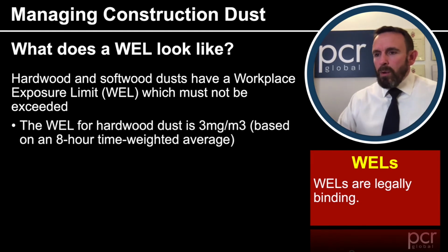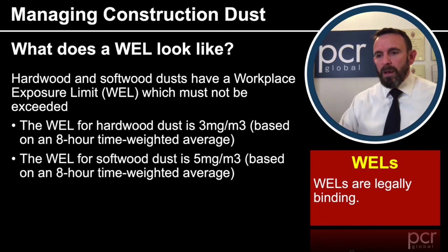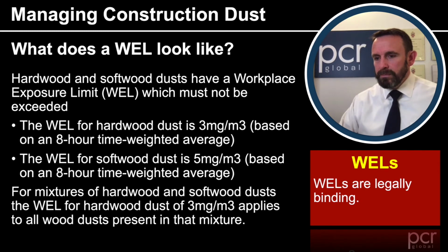So there are WELs for hardwood and also for softwood, and they also must not be exceeded. They're also legally binding. For hardwood dust, this is 3, so that's 3 milligrams per cubic metre of air, and for softwood dust, that is 5, so slightly higher. If hardwood and softwood are mixed, then the WEL for hardwood dusts must be followed.